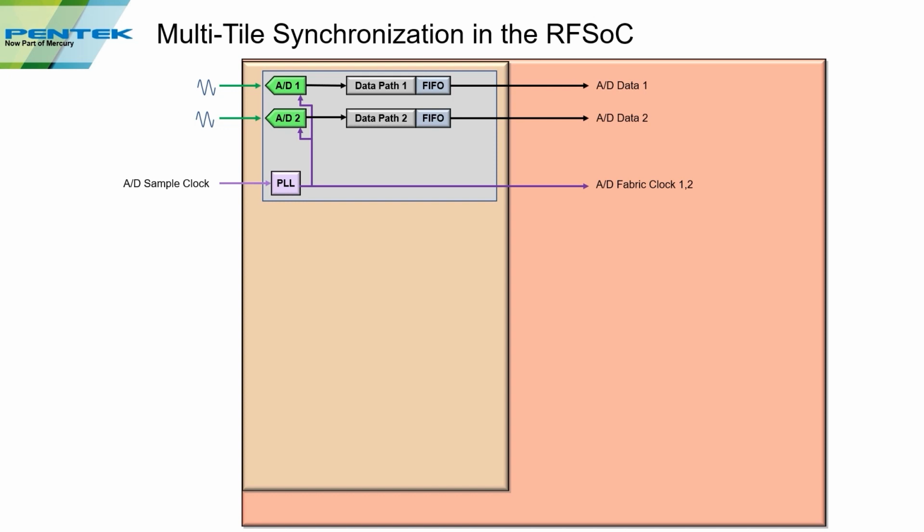But now let's add some of the signals you need for multi-tile synchronization. The first is sysref. The term is borrowed from what is used on JESD serial interfaces, but the sysref here is slightly different. The sysref provides a signal to the sync logic. Each tile has a delay circuit prior to the sync block, and that allows you to better match the sysref across all the different tiles.